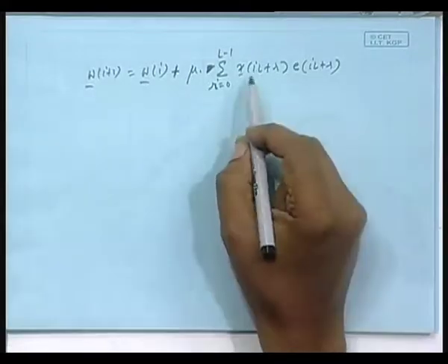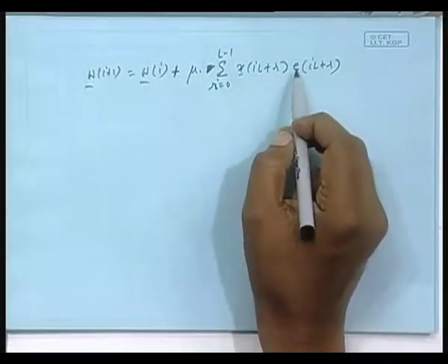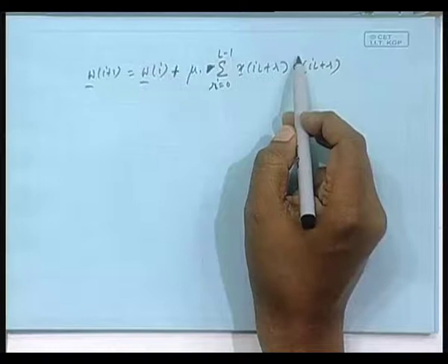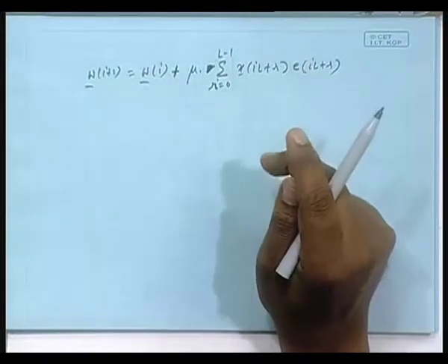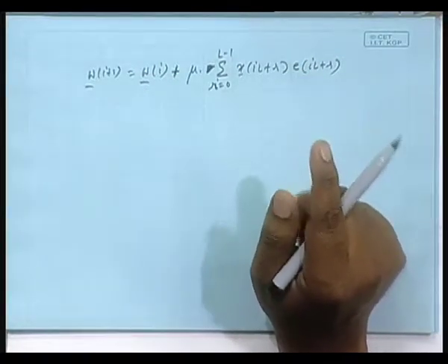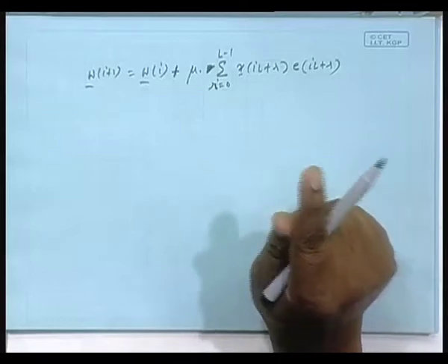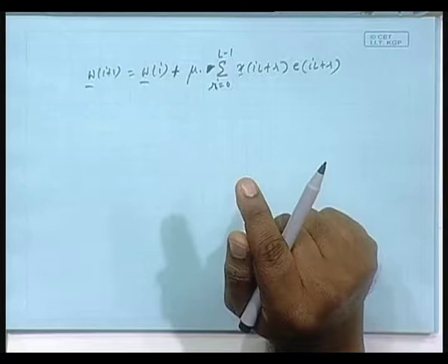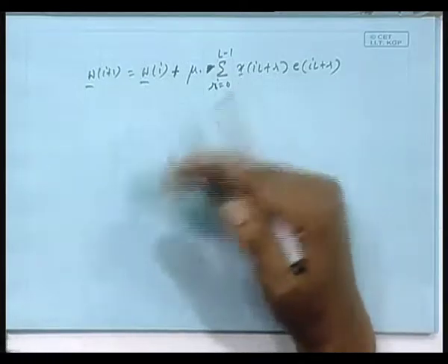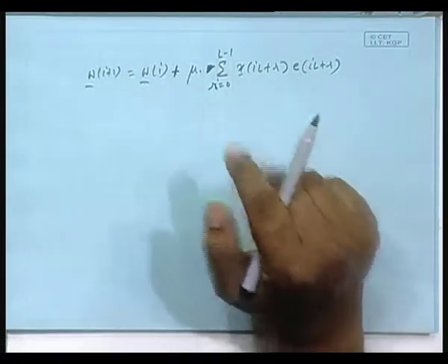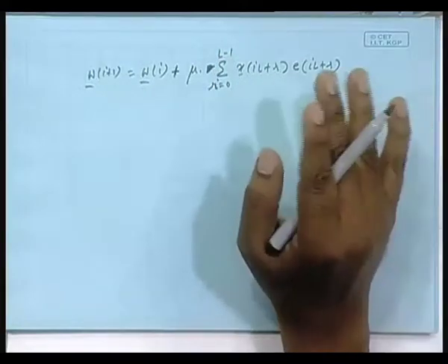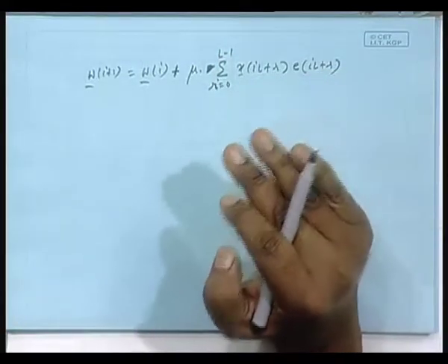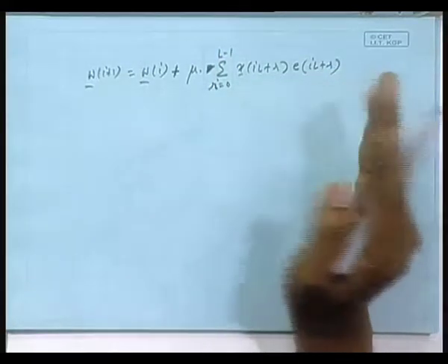In the complex case, this data vector will be as it is, there will be a star across, I mean on E, and in the filter part it will be W transpose x n, W Hermitian times x n. That was the only difference. We will extend this to the complex case as well. I think that extension from the real to the complex version of the block LMS algorithm you can do easily. That is not difficult, we have seen how the LMS case is, it will be so.